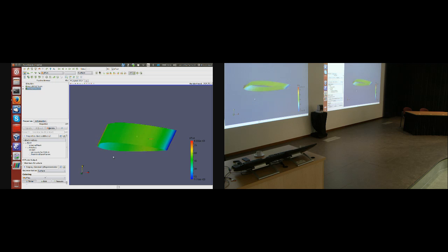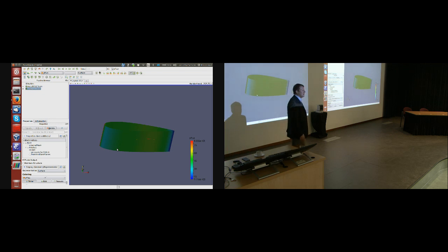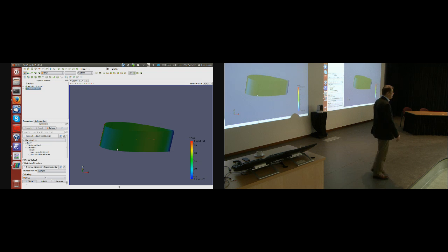Okay, so now people tell you, yeah, but your Y plus needs to be between, say, 30 and 80, but here you have Y plus of 9. Well, yeah, I do, because in the impingement point, my Y plus is always going to be very low because the velocity goes to 0. And at the trailing edge, where my flow does something silly and the mesh does not adapt, my Y plus is going to be silly. I don't care. What I do care about is whether Y plus is okay over the bulk of the profile. Okay? So here it is around 45, which is perfectly fine.